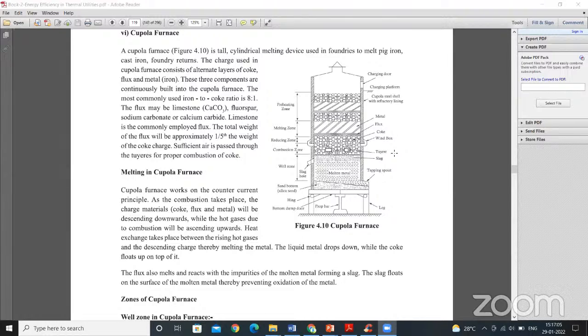But the main drawback of the electrical furnace is you may require a separate transformer for the furnace, because you can't connect the furnace with the normal supply. Most of the time it will be a thyristor controlled furnace, because the temperature can be changed with respect to the metal condition.